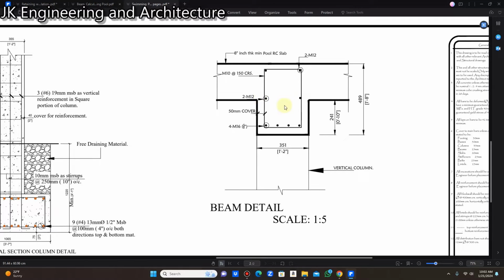If you know the modes of failure of a beam, a beam fails in two modes. A beam can fail through flexure, or bending, or through shear. So it is critically important that when you're designing a beam, you design your main reinforcement to carry the load, and you design your stirrups, in terms of your spacing, to withstand your shear. So shear and bending, that's for your beam.